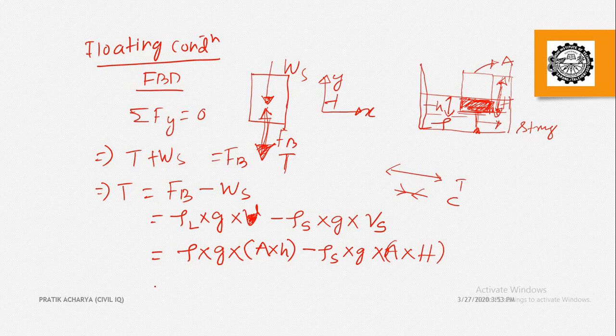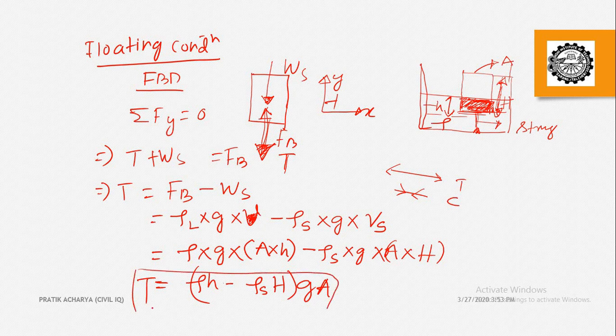Okay, so if you do this, it will come out to be density into small h minus density of the solid body into capital H, into g into A. So this is the tensile force developed in the string. Okay, this is one very good numerical.